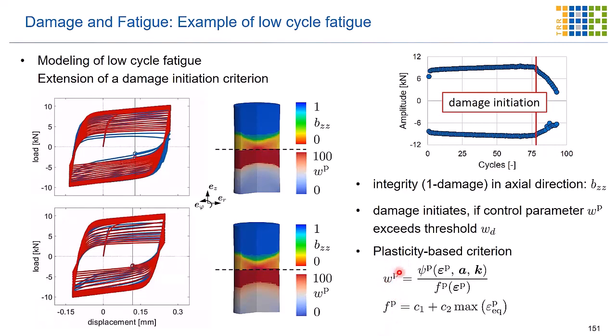So we control, or we observe, the developing plastic deformation. So we see there is some plastic deformation during every cycle. We then choose the most relevant parameters, put that into these functions here, to the potential into F. By that, we compute the initial damage initiation parameter, and that then allows damage to evolve here, B.